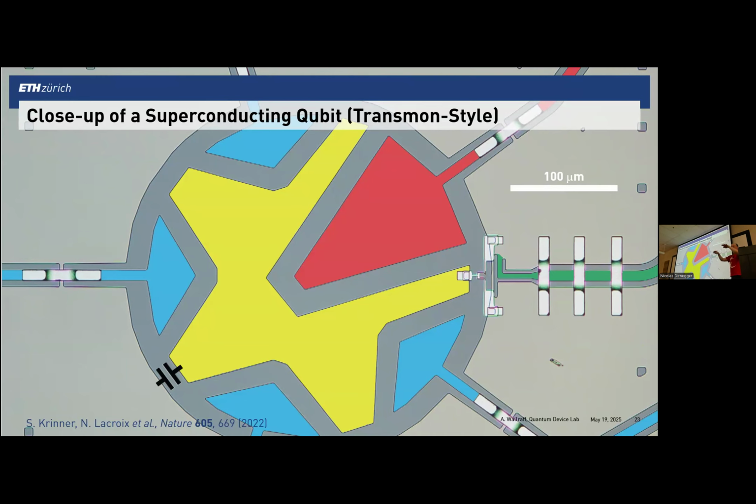barrier is likely not very homogeneous, because if you look microscopically at the surface of the film, it's still a bit granular, and likely some of the supercurrent through these tunnel junctions actually goes through the parts with the thinnest barriers, which have the highest currents, and this could also affect the performance of your device. But we've not looked at this very carefully, and to some degree, it's kind of magic that these aluminum Josephson tunnel junctions work as well as they do.